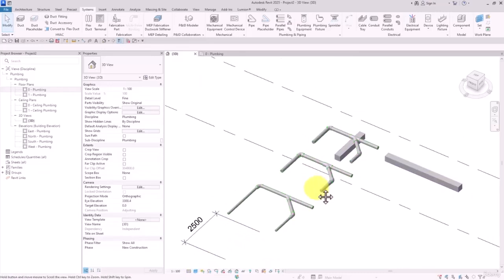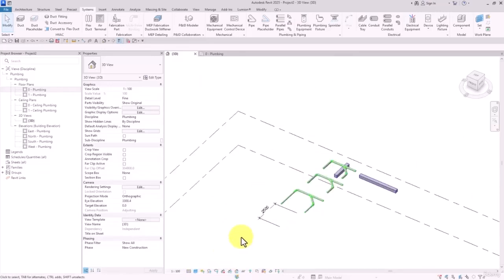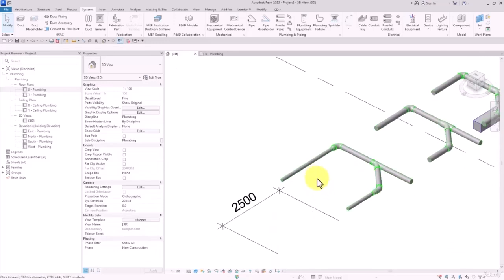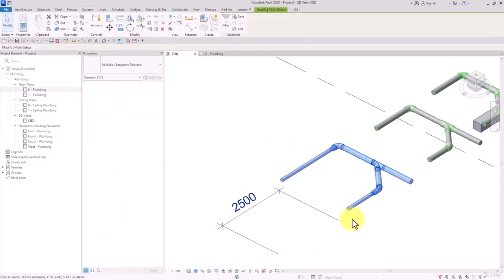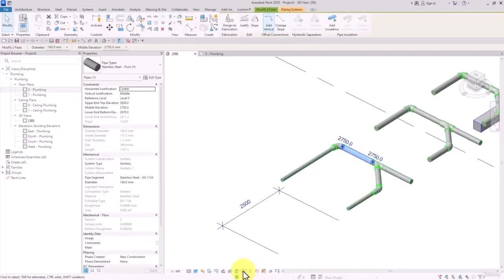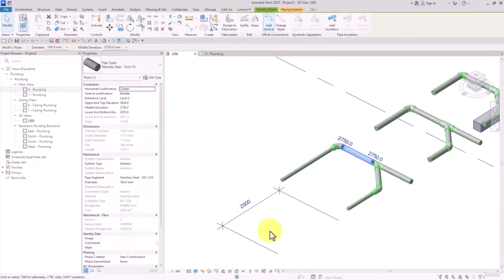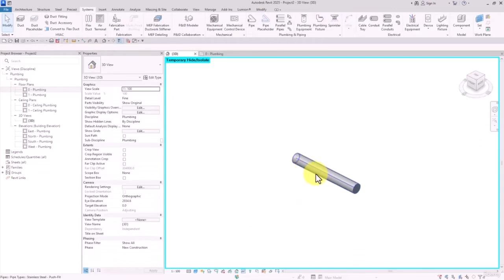All right. Next item down here is quite useful and by default is deactivated. It'll be activated when you select an object or multiple ones. For example, I'm going to select this pipe and then in this list I can see some options are activated. First one is hide elements, but obviously you can use this to hide the selected elements. Then we have reset. You can use this to turn everything back. Then we have isolate elements.